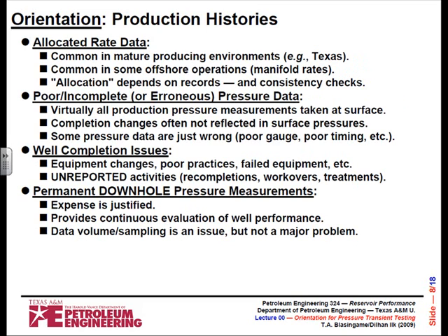Now, here's another problem. In Texas, you've got 500,000 operating wells. And in Texas, you're allowed to allocate data. You're allowed to report by lease, and then people back allocate by well. This is very common. It's also very common in certain countries where they split their production out. They're only looking at gross production, so you may only have a measurement a month that reflects reality. Just be very careful with allocated data.